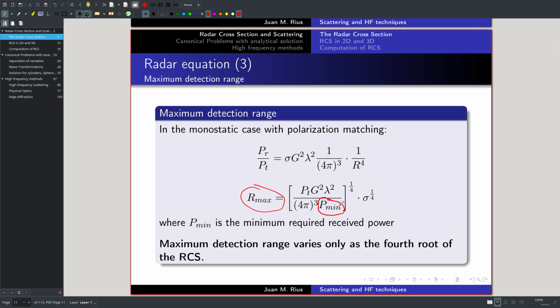This is the sensitivity of the receiver, the minimum power that the receiving antenna must receive to detect the target, and it can be very low because the receiver is very sensitive, but also because signal processing makes it possible to receive signal power that is even less than the thermal noise, due to intelligent signal processing or just old signal processing, but there are signal processing techniques that are able to detect very low incident powers.